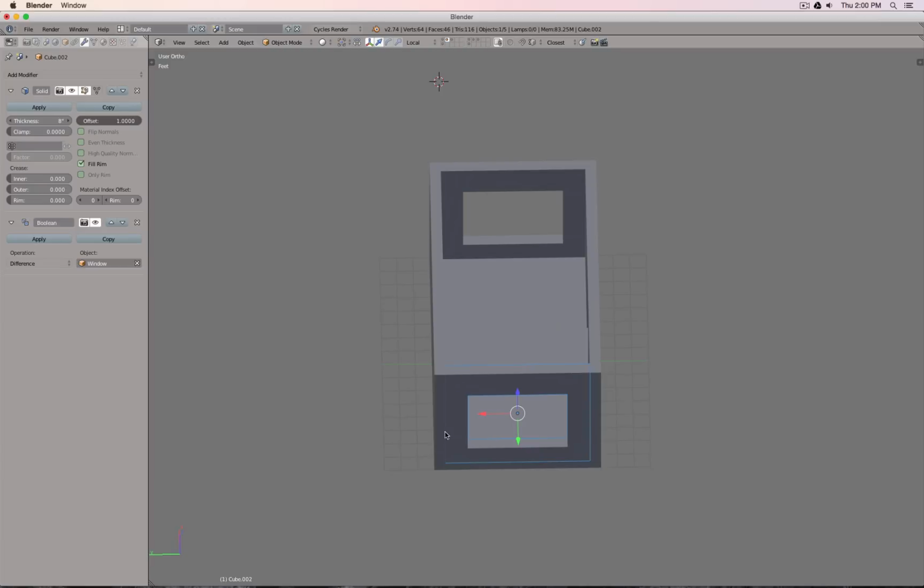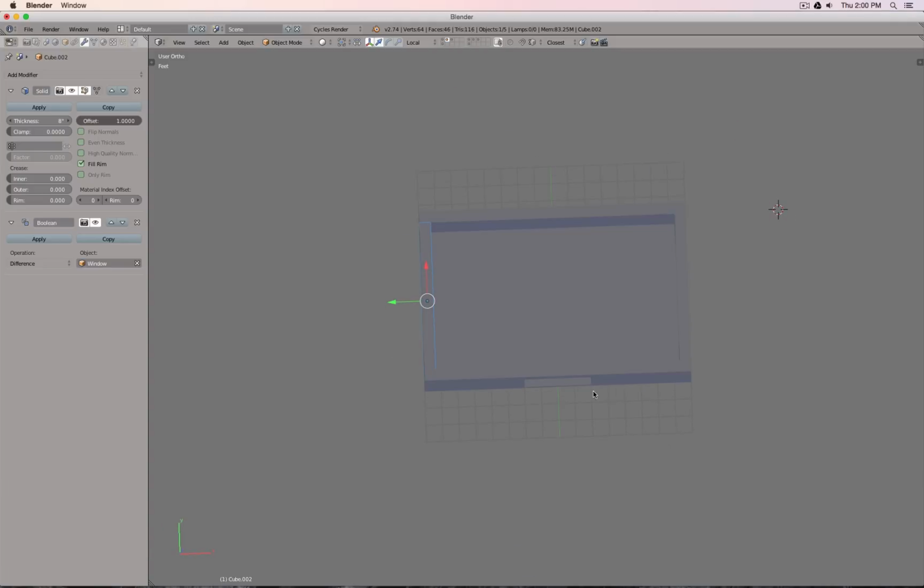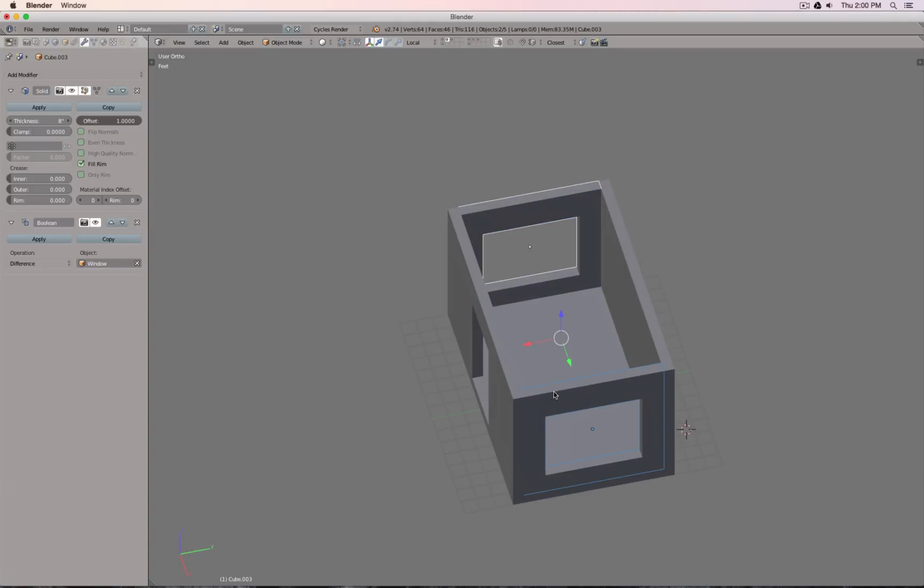We just want to make straight 90-degree cuts on the laser cutter, no extra sanding afterwards, and then simply glue everything together. So you see here in my case, I simply decided to make the side walls only as wide as the inner length or width and not the outer one.